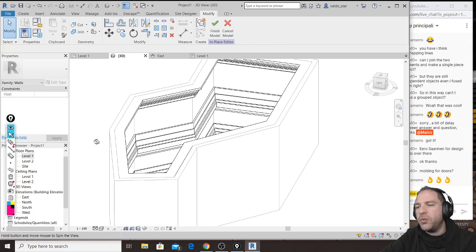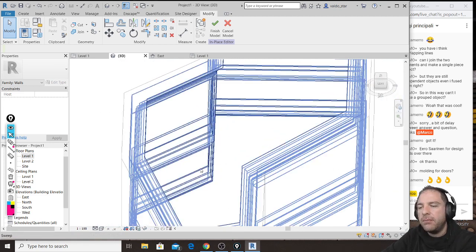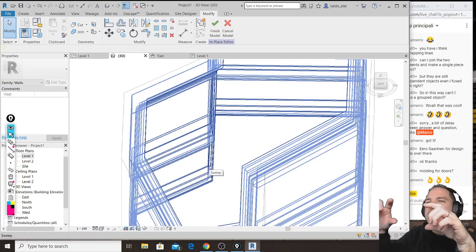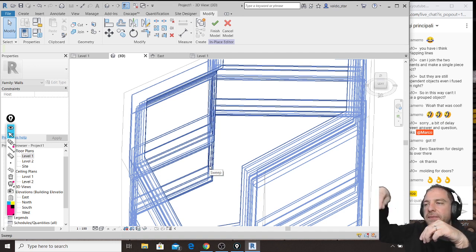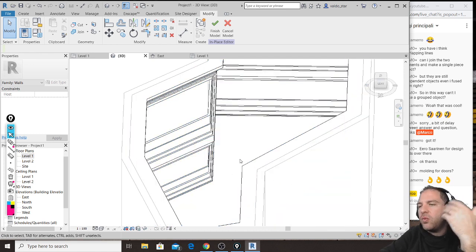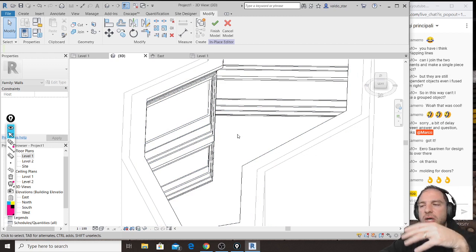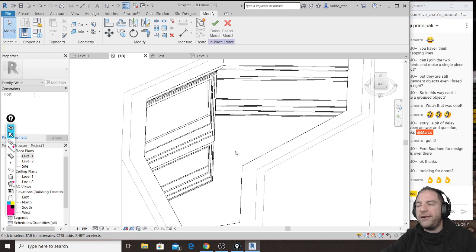Technically, with sweep, you can also add, let's say, have you ever seen those walls that not only have moldings, but in between skirting and the first molding, they have also a layer that is made in wood? So you can add instead just a thin rectangle along the sweep, and then when we will see materials, we can also add another material to that part so that you can have like the painting here, wood there, and so on and so on. Okay?